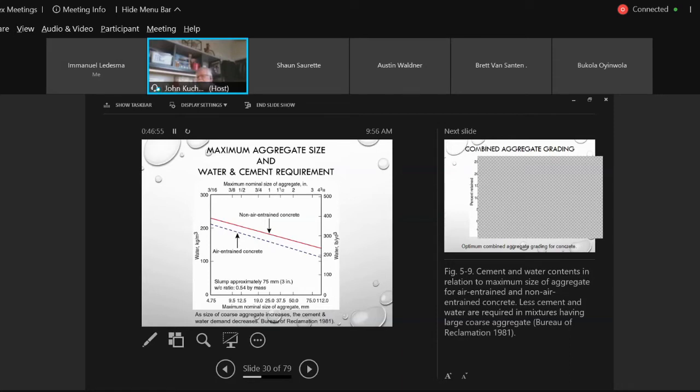But you also want microscopic small air bubbles in there. And that's called air entrained concrete. Non-air entrained concrete just means it'll have those microscopic air bubbles, but very little. Now, why are we introducing air entrained concrete versus non-air entrained? Why? Right, Mitchell, for when it freezes.